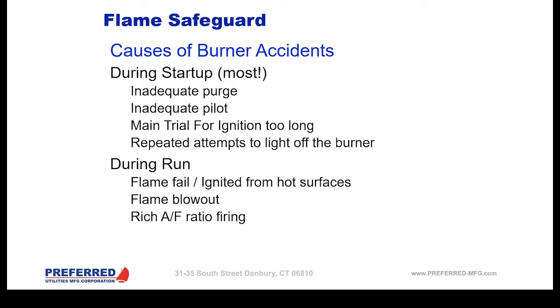Flame blowout, this could happen also for a variety of reasons actually, but again, with the proper flame failure response time, that will be caught, it will be locked out, and we'll let the operators know that an unusual and unsafe condition occurred. Now, rich air-fuel ratio firing.